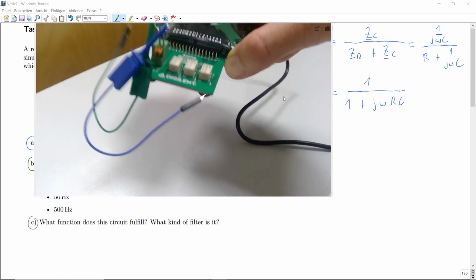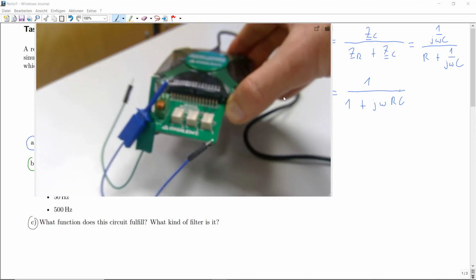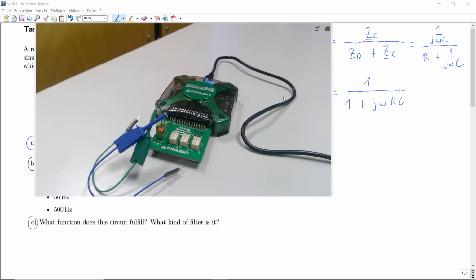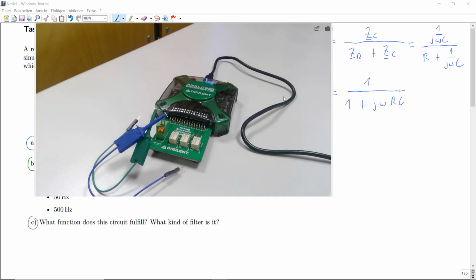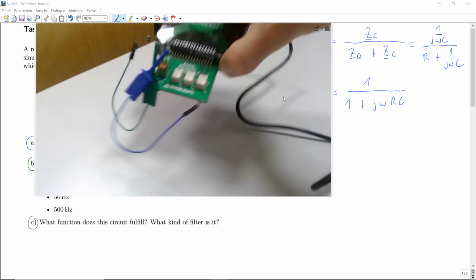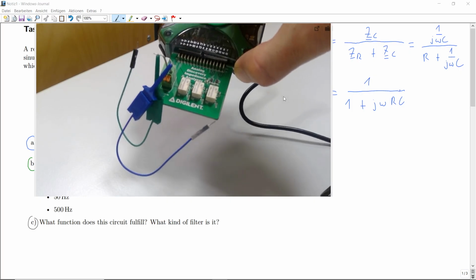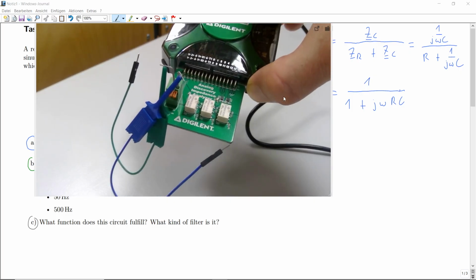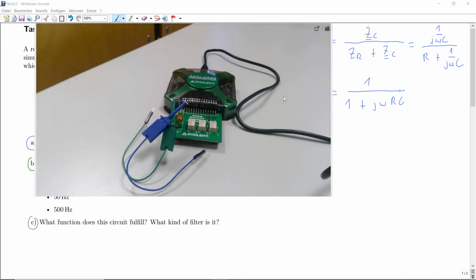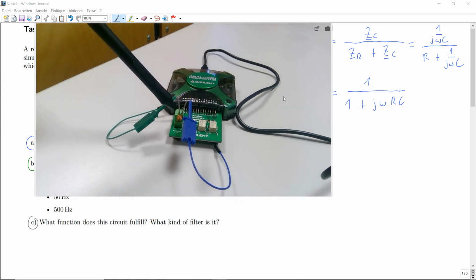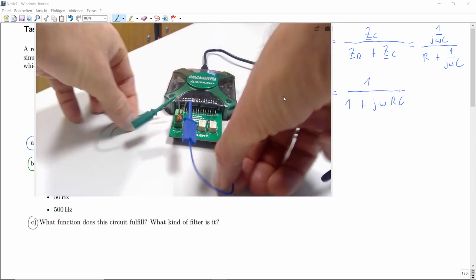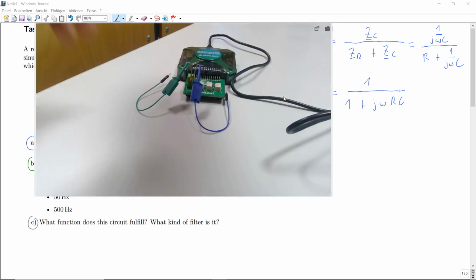So this is a USB to the computer, and at the front, it has some interface where you can directly connect cables, or where you can connect such breakout boards like this one here. And as you can read, this says it's some analog discovery impedance analyzer. So this helps us to analyze impedances. And in general, you could connect something directly to these terminals here, but this only works for small components. So what I usually do is I attach some more cables, and then I can connect like a breadboard.